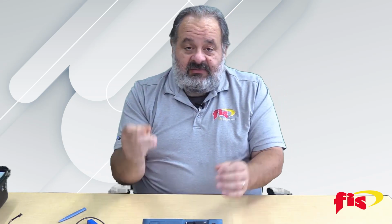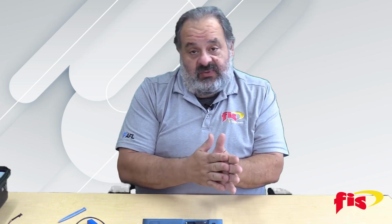So that's why we load up the front of that test with a length of fiber. And it's just a dummy load, really. It really has nothing to do with our test. It's just giving us the ability to test just before that first connection, which technically is making it the third connection because we're plugging our test cable into our launch cable. So whenever we test connectors with an OTDR, we're testing the mated pair. I remember years ago, certification-wise, it was about 0.75 dB was the pass-fail. Now today it's most commonly 0.5. Most OTDRs come loaded with 0.5 for reflective event losses.